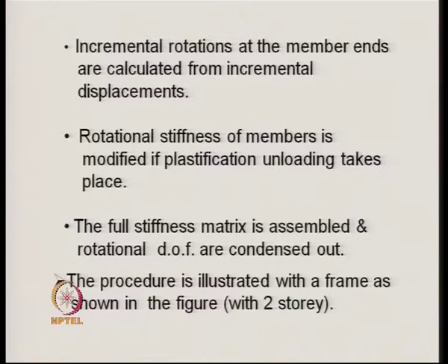Those incremental rotations are then added to the previous rotation to find the final rotation at the current state, and we see whether plastification has taken place at a particular cross section.